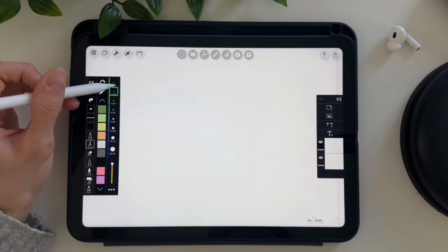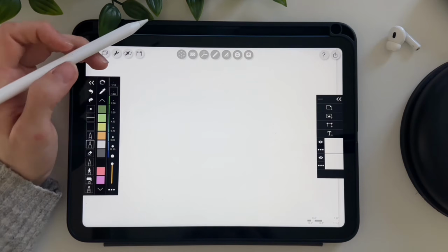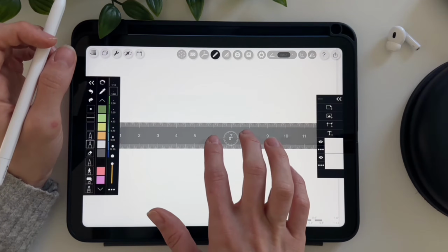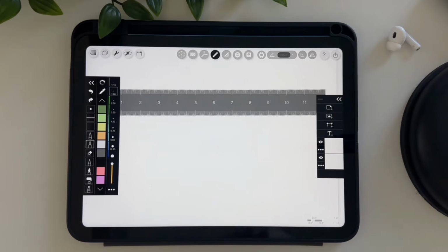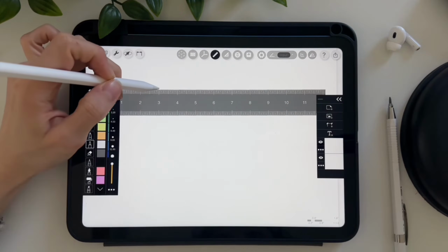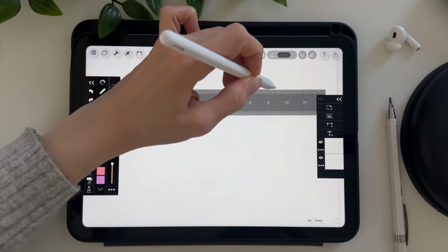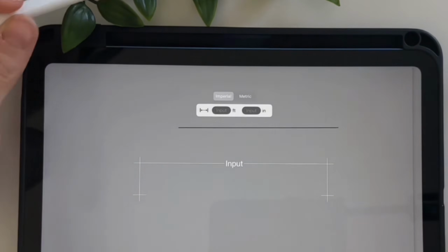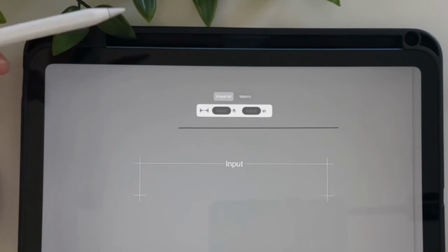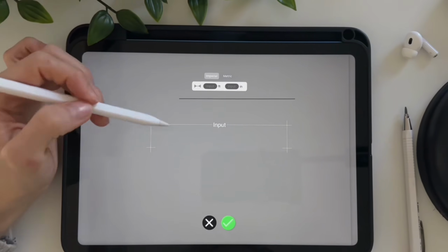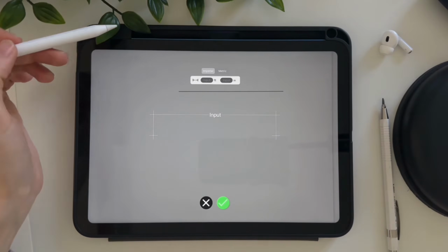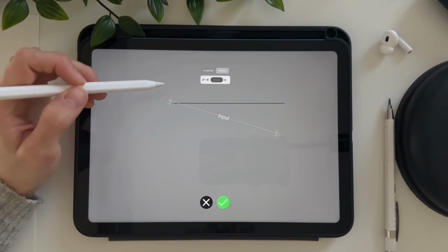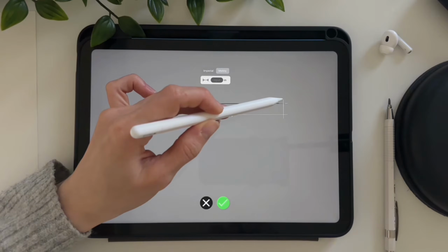I like to use the mechanical pen for drawings like plan or sections. Then I will start by drawing the walls. But before, let's set up the scale. So the wall is 350 cm. I use the roller here to trace a line, then I tap on the icon set scale, then you'll have this on your screen. Use the crosshairs and dimension input to set your scale using any known dimension. In this case, this is one of the walls of 350 cm.